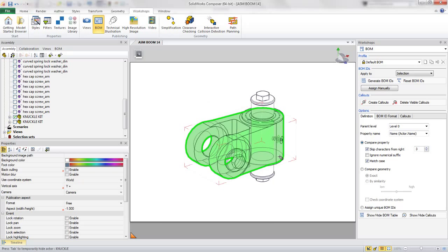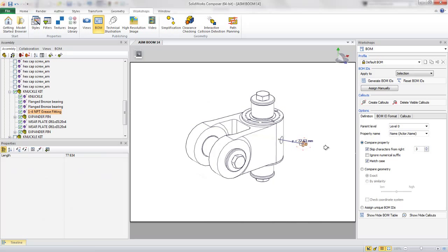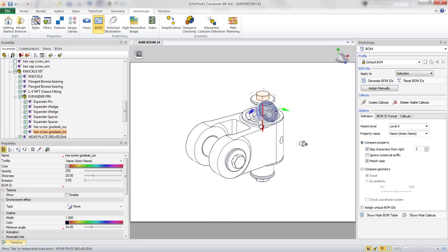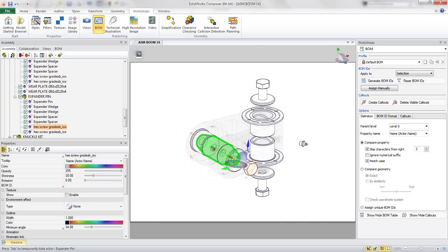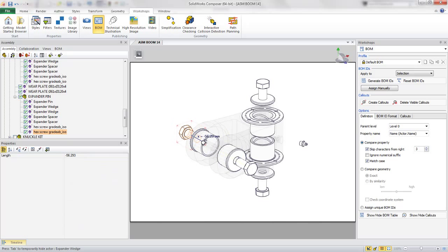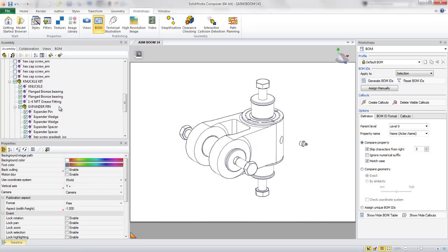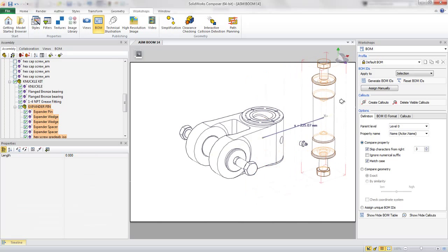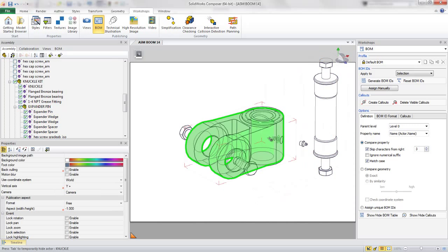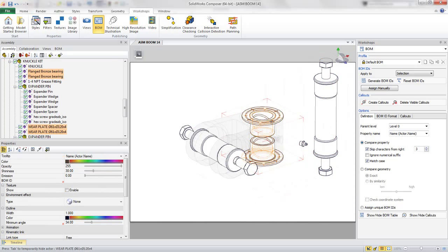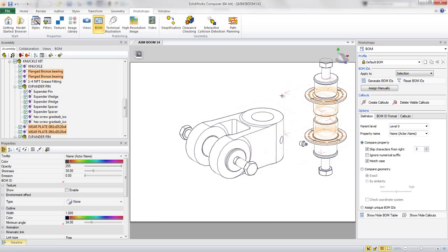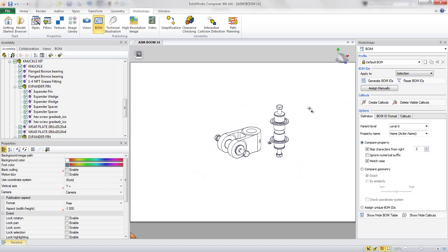Now we go ahead and get into moving the components using tools like the linear transform we saw before. Here we can see that using the tab key hides components out of view, making them easy to select. Sometimes, however, we want to grab more components than just what's on screen. We saw this a little bit earlier, but again, let's take a quick look at how we can select assemblies right out of the assembly tree. Now sometimes we move components and we don't get everything we're after. Another great tool for this is to transform based on the position of another component. And make sure that if we miss anything, we can always go back and make changes.